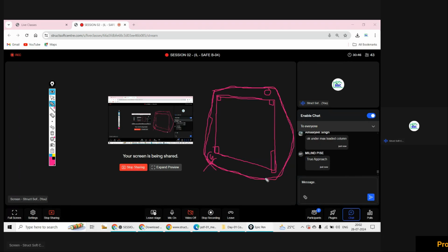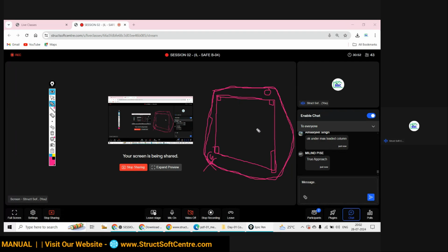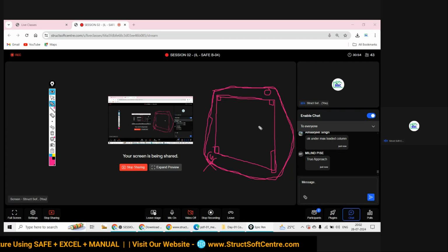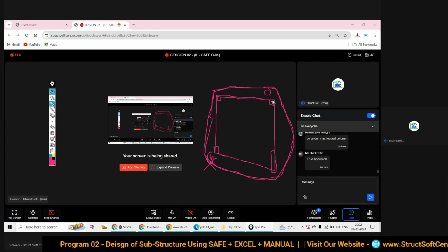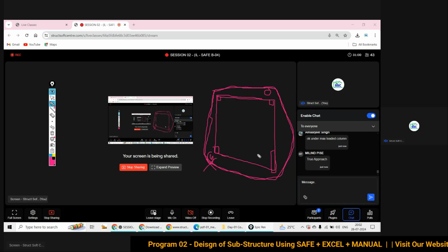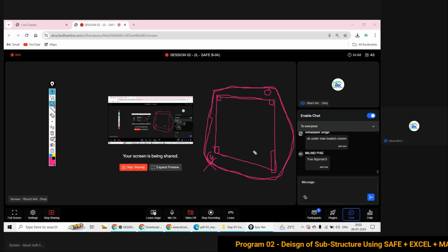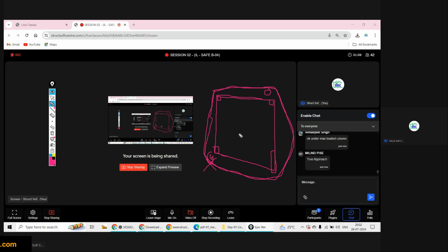So the structural engineer will do this. This is the column, so at four corners you are all suggesting to do the exploration. Yes, that is correct. As per our structural configuration, columns are coming at four corners, plus the geotechnical approach is what? Over the proposed area, at four corners there is a recommendation to perform the soil investigation, plus at the center, so that we can predict the entire area to be covered.